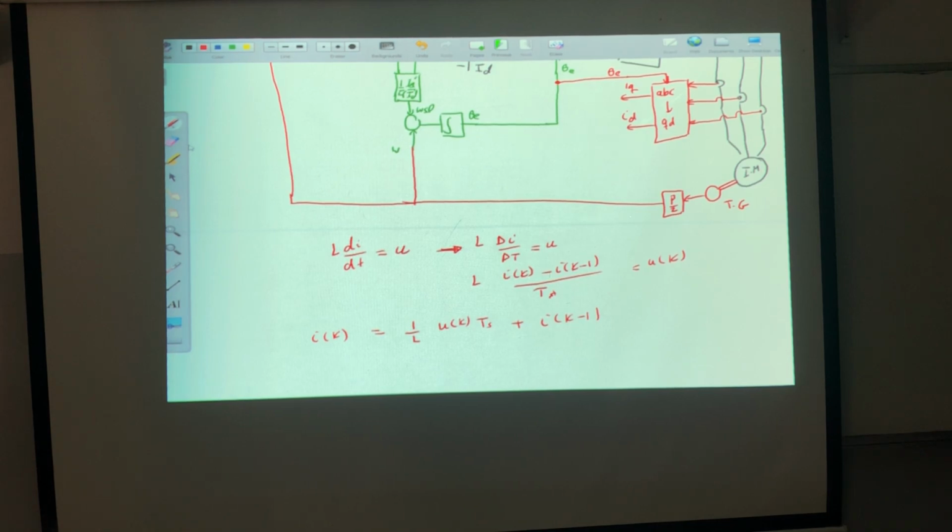Digitalization, digital control. Now, what you are asking, by the way, is something in MATLAB they call an algebraic loop. Algebraic loop is what? You are calculating something using something that you don't have. So, one of the simple solutions for that, I will add one time delay, and I will give initial conditions to this time delay. Either 0 or I will give it what? The rated value. This will solve the algebraic loop.